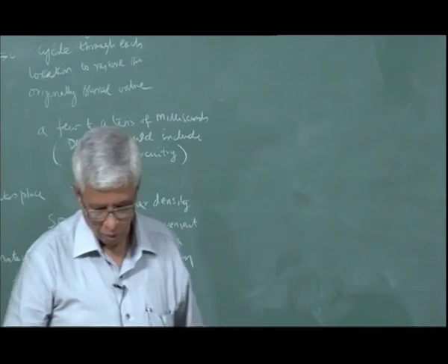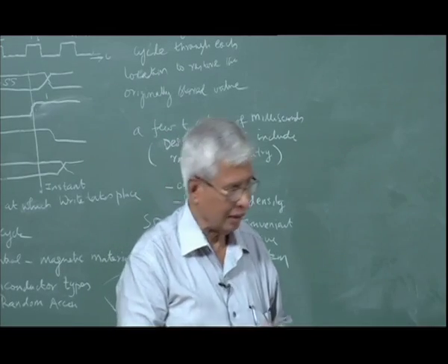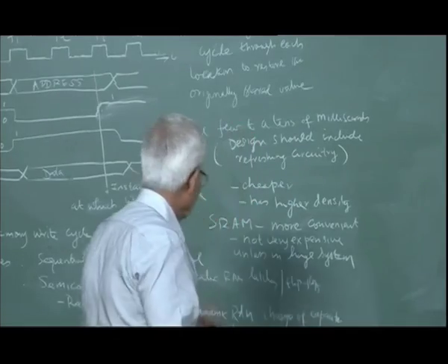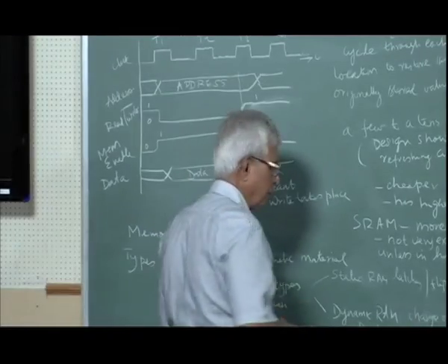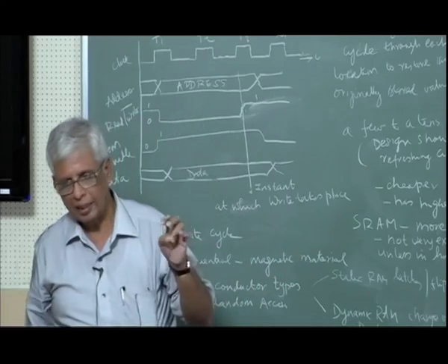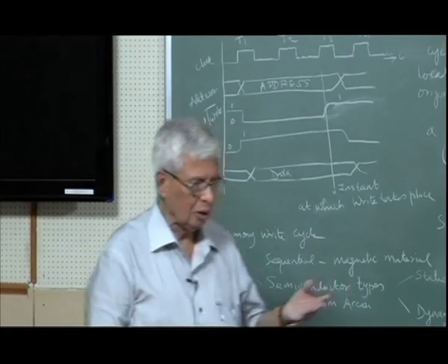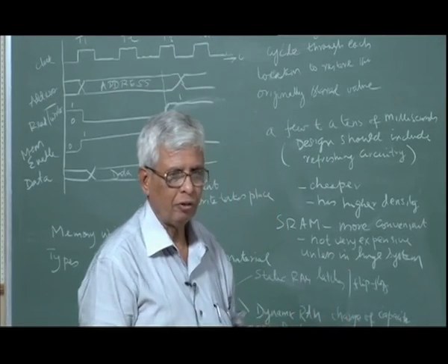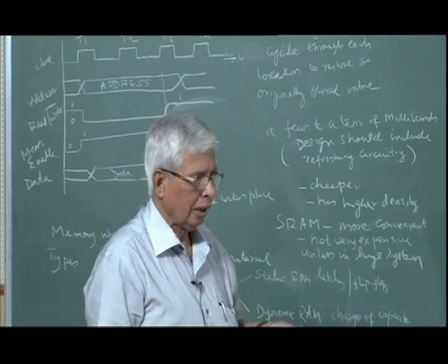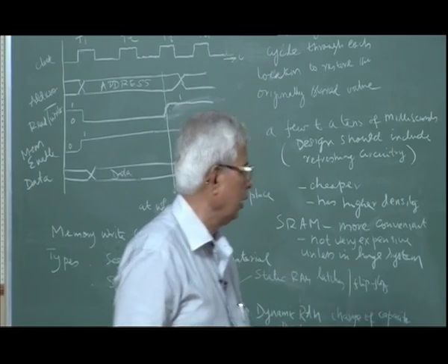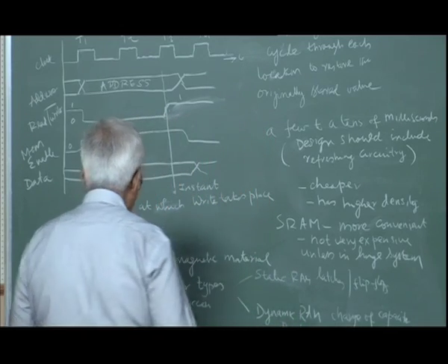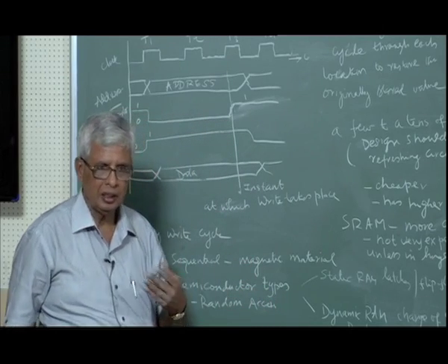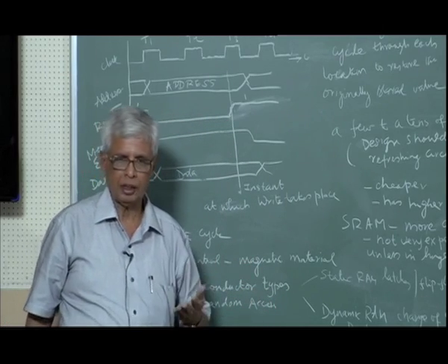Okay, what is inside? Because we said volatile memory, non-volatile memory. Non-volatile memory is the PROMs, read-only memories, where we store data and use it. You want to change it, you erase it and reprogram it. That we discussed in the application of combinational logic. Then today we started about read-write memory, where we can read and write, and the power dissipates. It is called volatile memories. When the power is taken off, whatever you have written disappears.